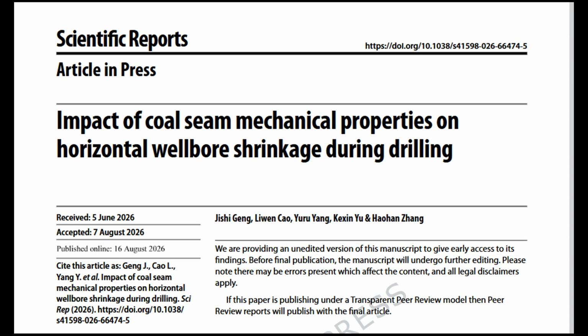This coefficient accounts for the volume change, dilation or compaction, that occurs when the coal shears, a critical feature for soft, fragmented coals. Equation 15 is the differential form of the flow rule. By integrating this relationship, the authors link the change in radius to the plastic strain increments, effectively showing that the radial and tangential strain rates are related through the dilatancy coefficient.